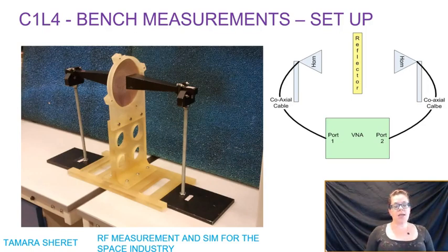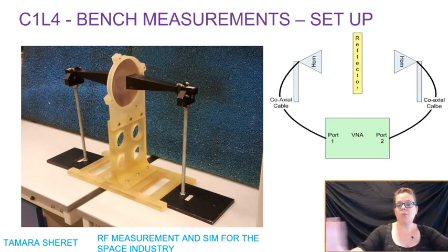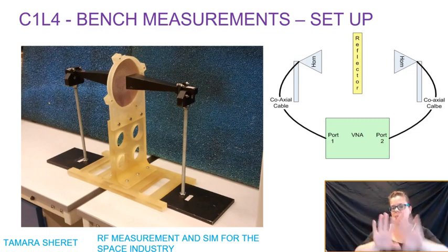The measurement that I was taking was actually a free space measurement because it was very low power that we were transmitting. So we just surrounded everything in RAM. You can see the flat RAM behind it. This isn't the spiky RAM, this is flat RAM. It was all the way around the sides and it had a lid as well with our little test unit.